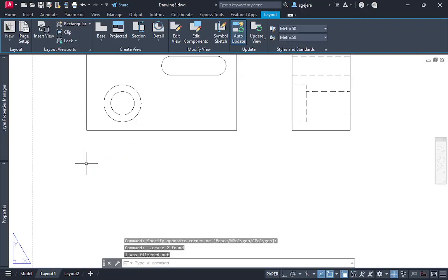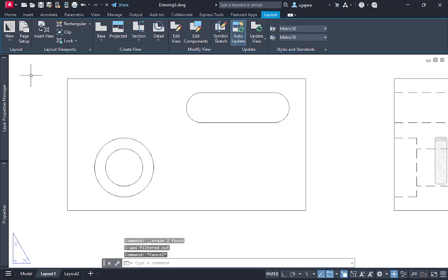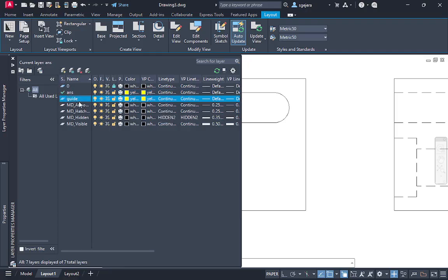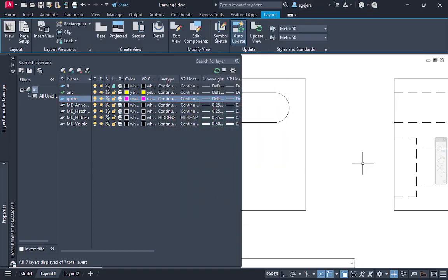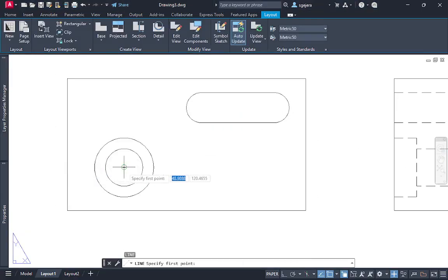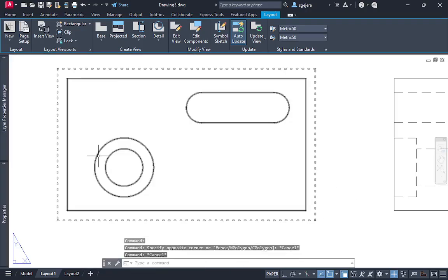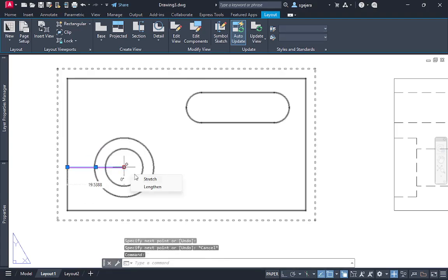Some students, ang ginagawa nila is, they first create a line, and they create the line in such a way na nasa new layer siya. Like, for example, let's just say guide. And I change this color. Gawin ko siyang pink para lang alam talaga na guide lang siya. Then, hahanapin nila yung lines na to. Kumbaga, properties, layer, guide. Magdodrawing muna sila ng line. So, let's find this one. Tapos, drawing tayo ng dire-diretso pa ganyan. Then, extend this line. Pwede ganito.